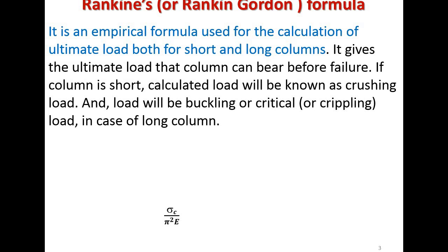To overcome this difficulty, Rankine derived one formula that is an empirical formula. That formula can be used for the calculation of ultimate load both for short and long column. It gives the ultimate load that a column can bear before failure. If the column is short, the calculated load will be known as the crushing load, and the load will be the buckling or critical or crippling load in case of long column. That formula is derived by some mathematical formulae,